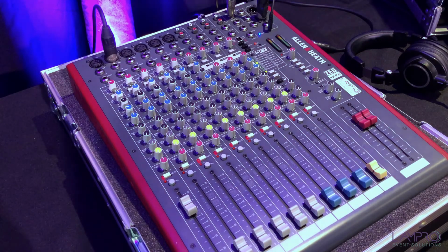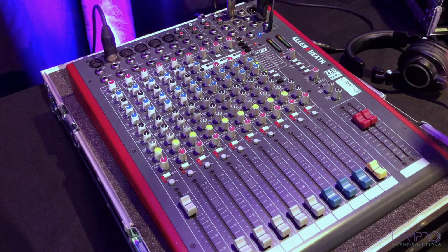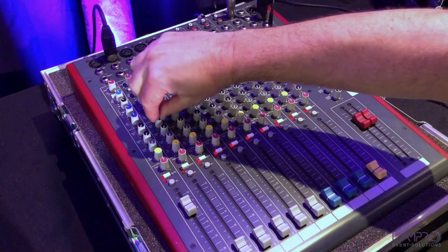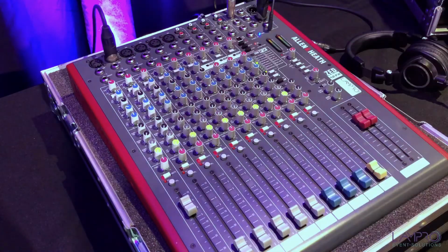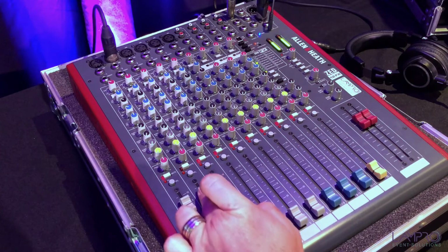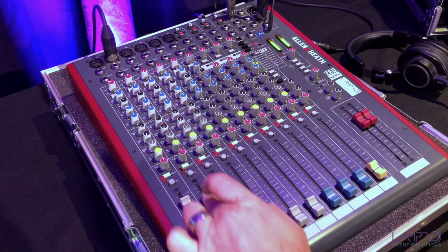At the moment, I've got a speaker connected to the aux1 output, and if we open the aux1 master, and the aux1 rotary fader on the designated channel where we've got the 1 kilohertz testing tone, you can hear some of that coming through the speaker, but when I adjust the fader, you won't hear any difference to the overall level that's being sent through to the speaker.